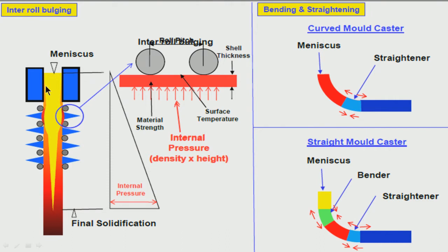Again, there is not only the liquid slag, some of the liquid slag will solidify also because you are cooling it. So, there will be initially a solid slag, then there is a liquid slag. What is the relative thickness of this solid and liquid slag? All these are important. They will give you the lubrication, they will give you the heat transfer.